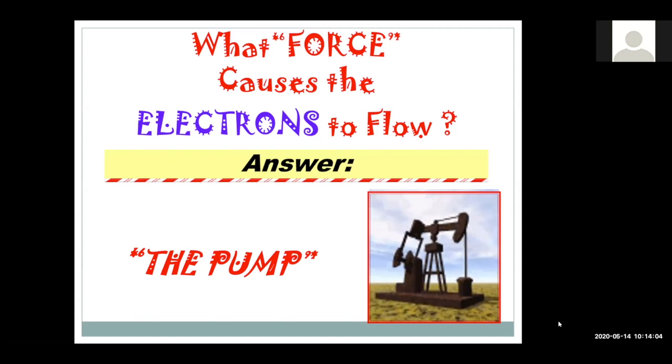Every circuit starts with the transformer and could be traced back to that transformer that is putting out the hot wire, if you will, and it's going out to the load, and then back to the transformer, and we'll look at that more clearly. Back to the transformer is very important, and I think that sometimes we don't understand that, but it is very important. The neutral can shock you, the neutral can kill you. The neutral is very important. If you get in that circuit, then you become part of the circuit. That's not a good thing.